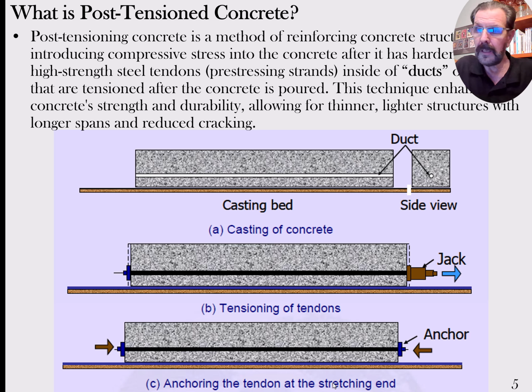It's the same kind of strand, but in post-tensioning, they will generally coat that pre-stressing strand with grease and then put it in the jacket, because we definitely don't want the strand to bond to the concrete there, because we're relying on an anchor and a chuck fitting at each end, or both, having a chuck fitting where we can pull it up at tension and secure it in there, embedded in kind of a pocket.